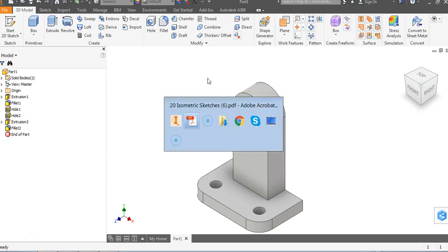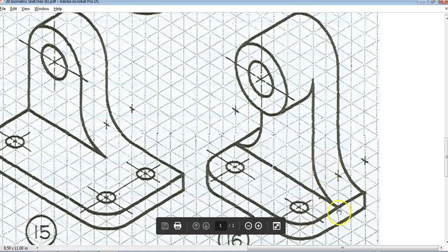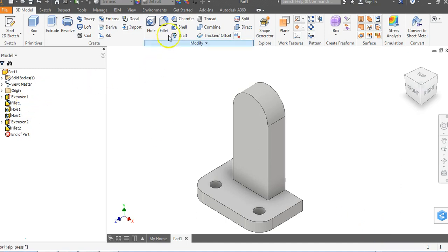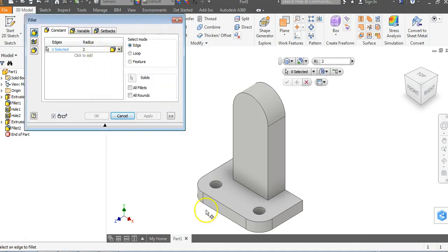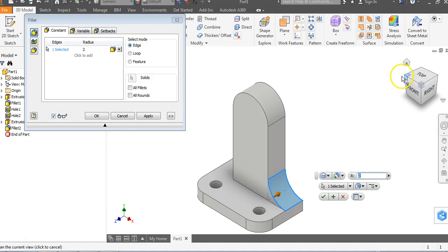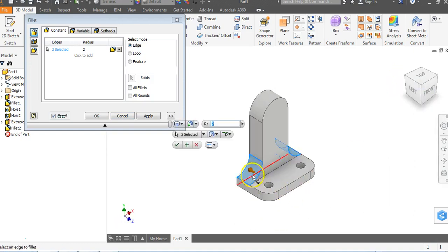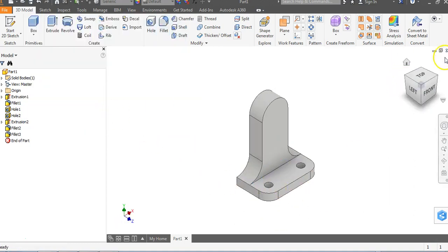So we also got to use an additive fillet here, where this is going to add mass. So down here, what's my radius going to be? From this vertical line here, I come over 1, 2. This additive mass and this additive fillet is going to have a radius of 2. So we're going to go back to fillet, and we have 2. I'm going to click on this line, use my view cube and flip around, click on that line, say OK.